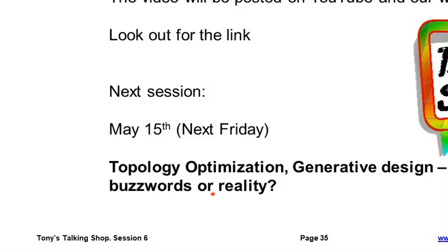So it becomes a dynamic type of behavior. The assumption is that it is high cycle. I don't have any experience with a low cycle fatigue approach with vibration fatigue. There probably is some theory out there somewhere, but I'm afraid, Badri, I will do a little bit of research when I curate the questions to see if I find anything, but there's nothing to my knowledge. It's assumed to be a high cycle fatigue type of approach.